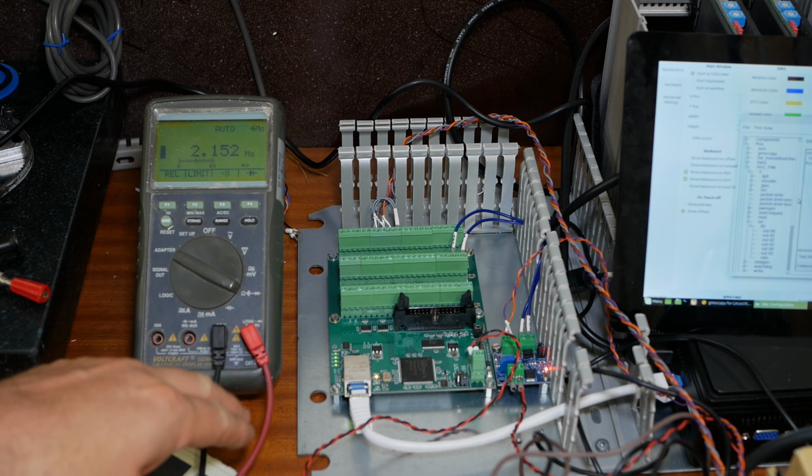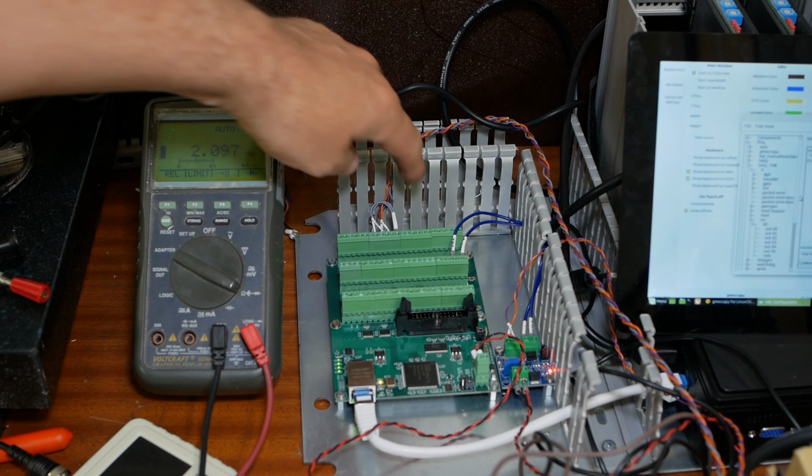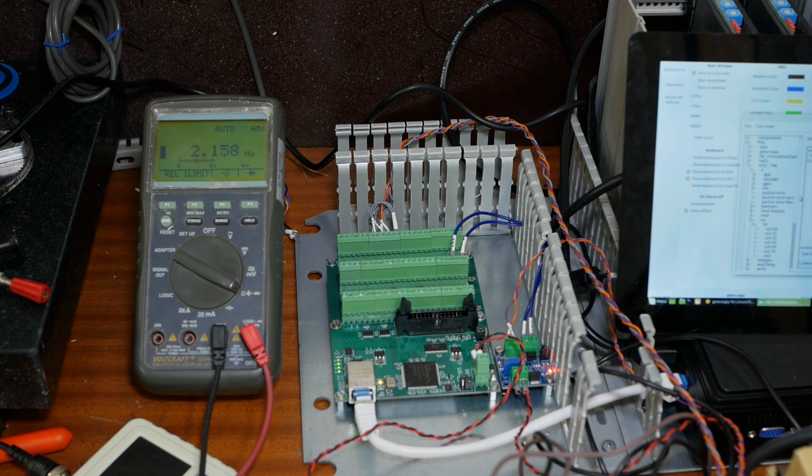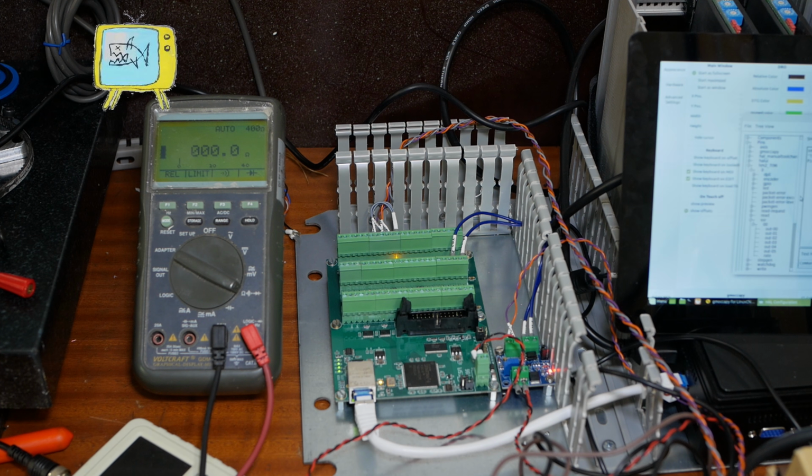I've now set up the multimeter across this switch, which is switch number 0. As you can see, when it's in the off position, being some sort of electronic solid state kind of switch device, it's not actually an open circuit. It's got 2 megaohms of resistance. And then if I switch it on, we'll close the circuit, light comes on. Now the problem I've got with the VFD is that that off signal is not off enough.